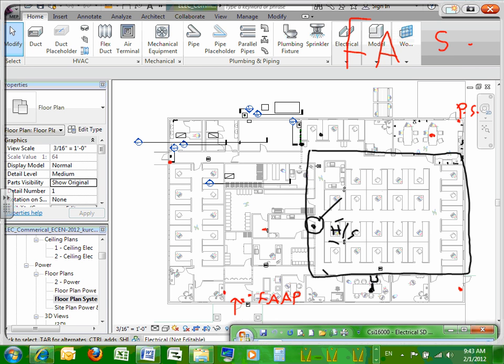One reason for not putting a horn strobe in restrooms and conference rooms is they're kind of a small space. You get a horn in there, even if it's a low audible horn, it's such a small space you'd blow your eardrums out running out of that place. So strobe only, visual only. You'll see that flashing light and you'll know to get out of there. Not to mention there's tile and a bunch of... Yeah, exactly. It'll echo.